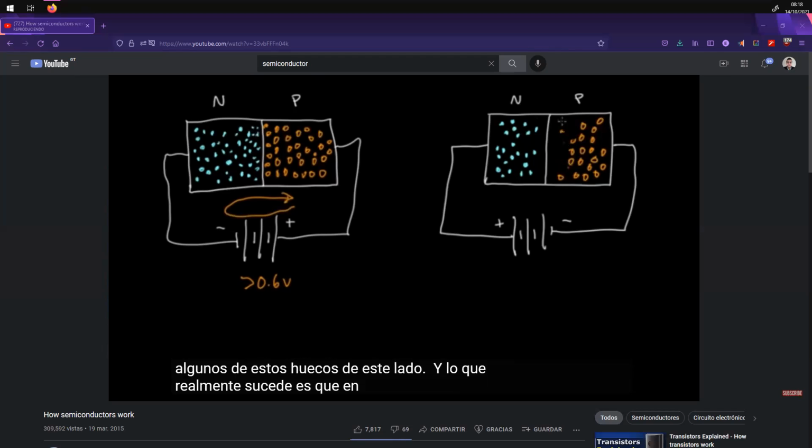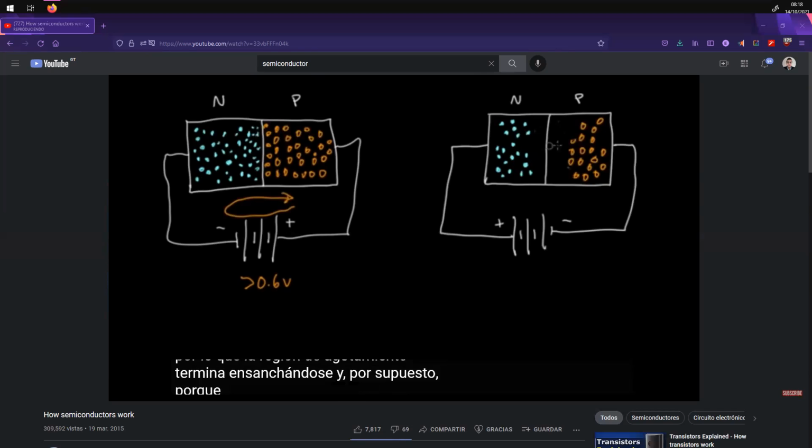So in this scenario, the depletion region will actually get wider, because electrons are leaving the N material, and electrons are coming into the P material as it becomes a little bit negatively charged because of the negative terminal of the battery, and they fill in these holes. Of course, because there are no charge carriers in this whole region, this area is going to act like an insulator, and no current will flow here. And so this PN junction has this really interesting property, right?